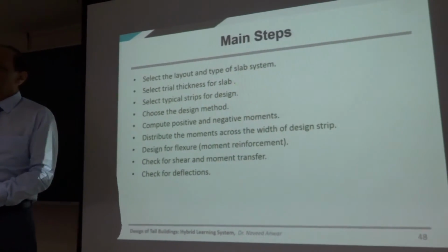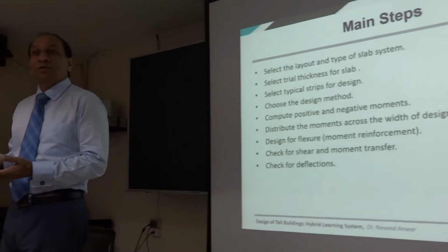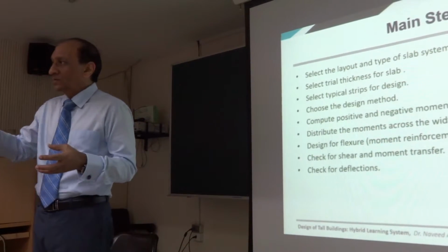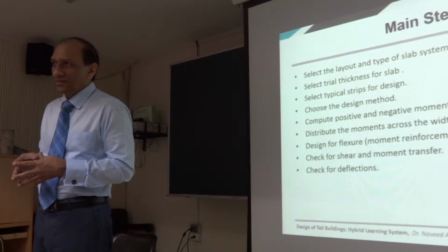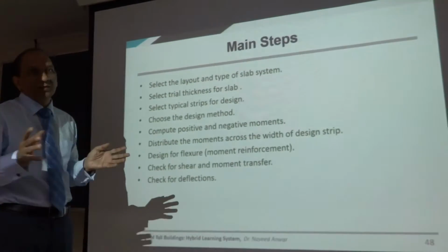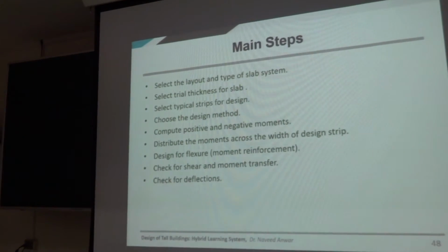Building is 30 floors. You don't need to design slab on all 30 floors. You just pick up typical floors and then design typical strips, right? So you have to be sensible, intelligent about it, otherwise you will spend all your life designing one building.